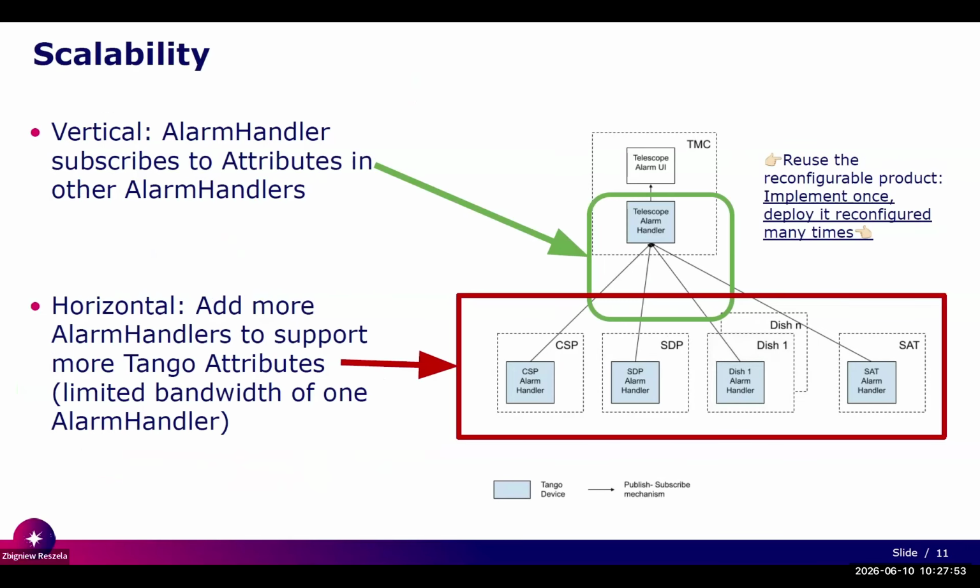They help the operator to assess the situation. All right. Scalability, I just mentioned it, right? We can chain these alarm handlers, the Tango devices, because we're essentially just dealing with values of attributes. How hard can it be, right? It's simple. The beauty of this whole system is it's just looking at values of attributes or of their quality factors. Pretty simple, pretty straightforward. These rules, everybody can write these rules, which means our hardware engineers can say, look guys, when this actually happens on my FPGA, I think this is the moment when you need to take action.